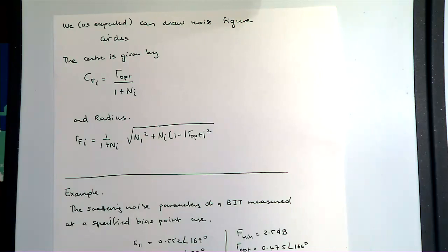Maybe your transistor's not unconditionally stable, right? So therefore, you might want to choose a different set of characteristics, where you've got a different gain and a different noise, but you achieve some other desirable properties for the system that you're developing. Maybe the voltage standing wave ratio is too high or something, right? And that's the reason why we do that. Now let's look at this particular example.